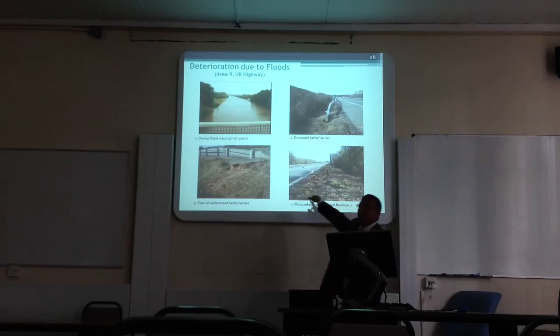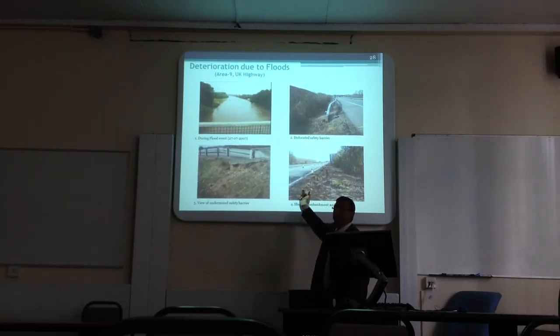If it goes further down, then of course there is an impact of water on the subbase. And if there is a weaker zone below the subbase, and the water was standing for a long time, then of course it is deteriorating in this berm, and eventually the whole road will fail.